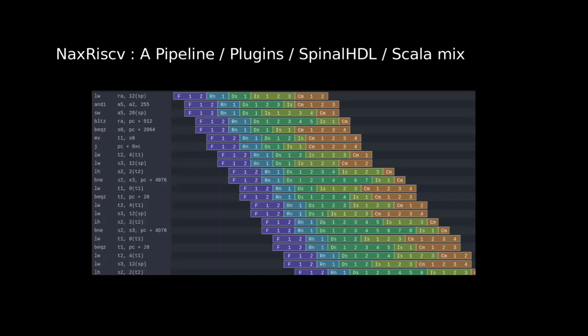So, yeah, I will, during this talk, use NaxRiscv to talk about the pipelining API and the plugin API it implements, and dive a bit into the Scala and SpinalHDL interaction.